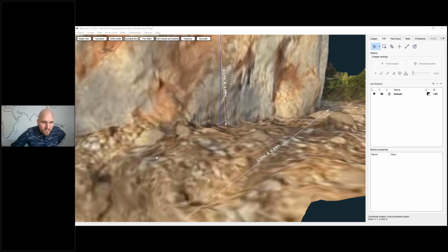Mr. De Souza is asking again, to run this new 3D Survey application, will we need a new special video card like NVIDIA? Yes, so okay, 3D Survey will also work if you don't have an NVIDIA GPU, but if you have an NVIDIA GPU, 3D Survey will be able to use CUDA. And all the data that I showed were calculated with CUDA support.